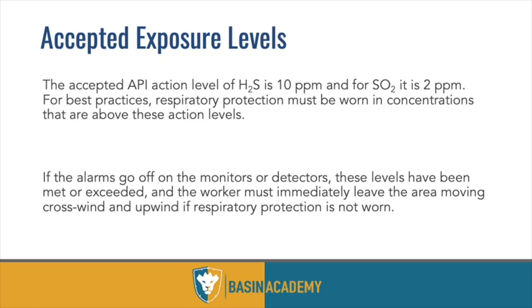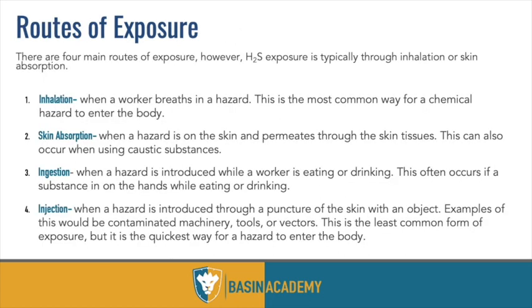Routes of exposure for both gases. Inhalation is the most common, by breathing it in because it is in the air or mixed with the air to some degree. Skin absorption can happen if it's in liquid typically. If you're a water hauler or an oil buyer or a roustabout, someone who's cleaning tanks, things like that, it's possible to get it on your skin.